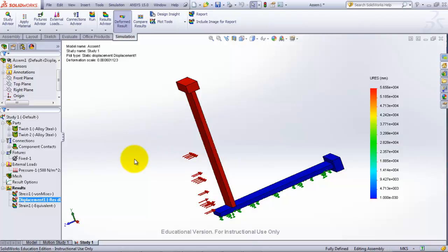All right, so using those techniques, the soft springs and the draft mesh are two key things. Unless you're confident it's going to work the first time with the setup you have, I would even run that the first time just to make sure everything looks good. But it's probably good just to run with your basic conditions and a good mesh, and then if it does fail, come back, use the soft springs, and use the draft mesh so things can fail quickly, and you can get some information about what's going on. Hopefully things are just flying away. You need to lock them in a little bit more with the fixtures.